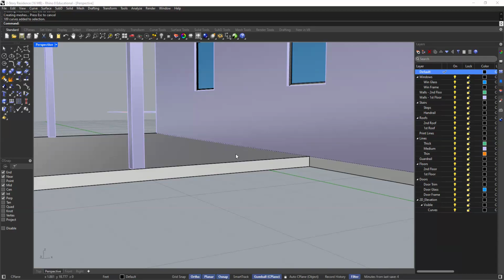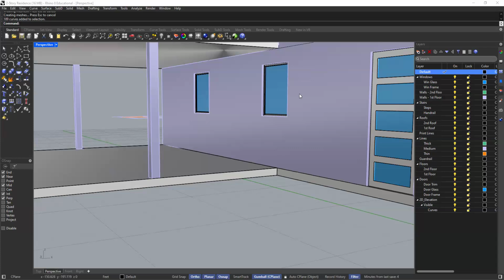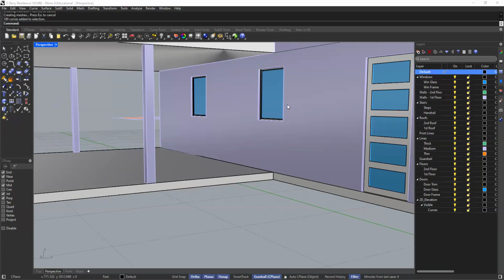A floor is made up of a bunch of different things. There are a lot of different structural components that go into a floor, and the very top layer of that floor, what we all walk on, is known as finished floor. So a floor plan goes 4 feet above the finished floor. That's the typical height. If a floor plan does not specify a height, then it just assumes that it's at 4 feet.